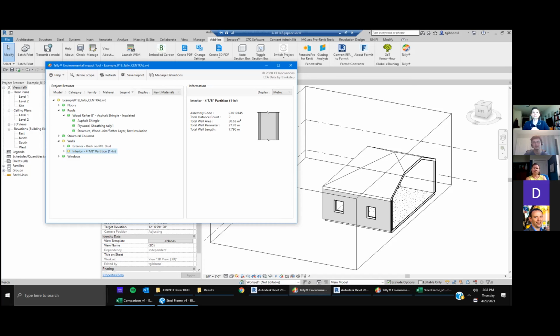So I'm really hoping that in my career more and more I can start to, because we get honeybee and we do all this super cool stuff on the operational side, but how can we get more facile at the embodied side to say, hey, if you make that decision, the payback period doesn't make sense, because of the output in embodied CO2 versus what ERCOT's going to give you over the next 30 years of your operational. It's like, don't put shades on, just get Meco shades and take a couple windows out, or make your solar heat gain coefficient 0.25 instead of 0.35, and you'll save all that stuff that you're trying to tack on.